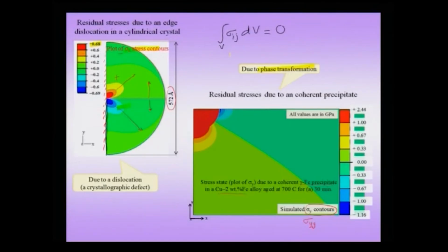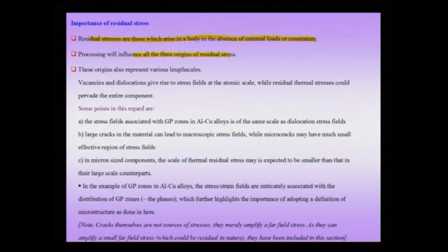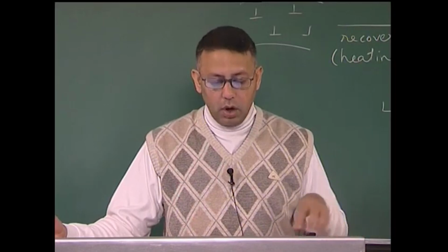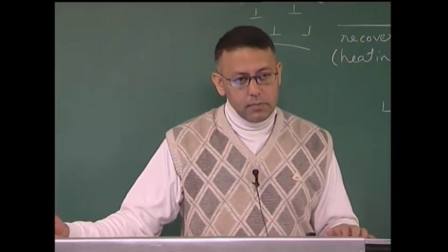When I am talking about three origins, I am talking about those arising from defects, those arising from phase transformations, and those having a thermal origin. Therefore, when I am doing a thermomechanical treatment, which could be rolling, forging, hot rolling, etc., giving rise to my final product or a component, then this processing will actually affect all three origins of the residual stresses. So, this has to be kept in mind.